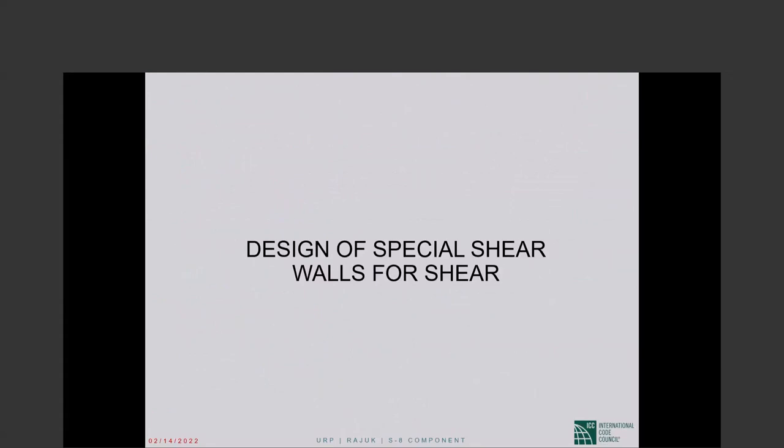Okay. Now is material that obviously has not been discussed before. Shear walls, like any other structural member, have to be designed for shear and also for flexure and axial loads. The flexure and axial loads go together, as in the case of a column.